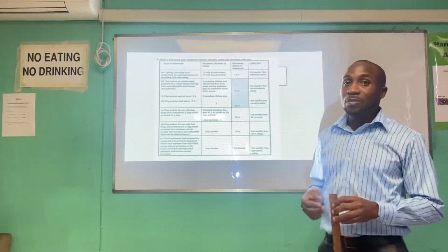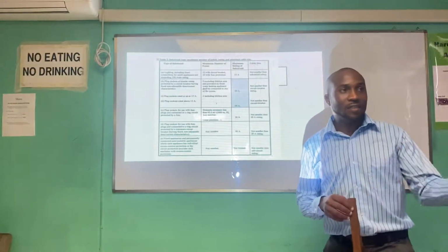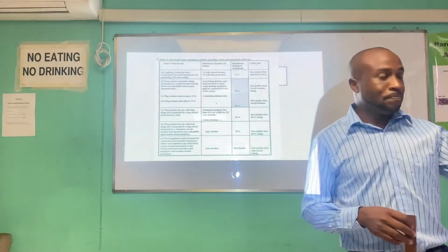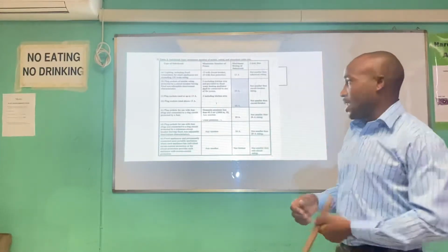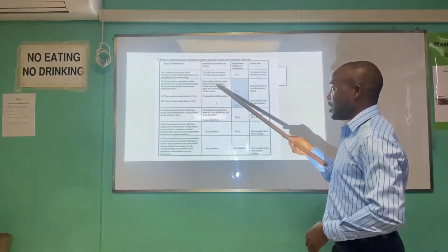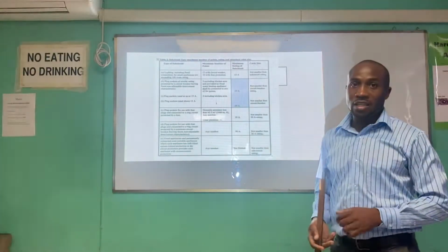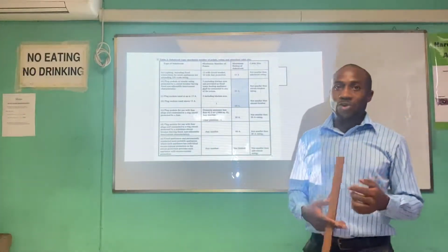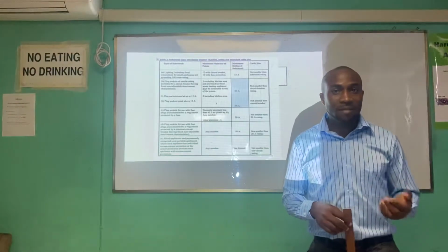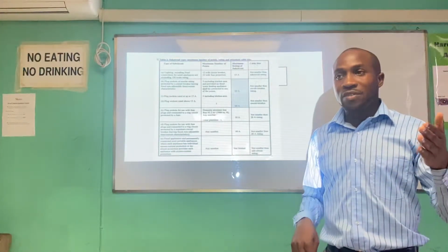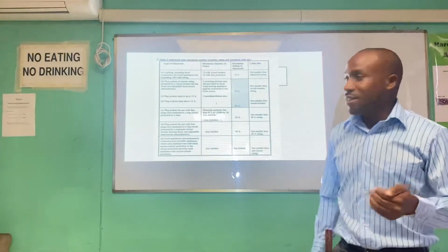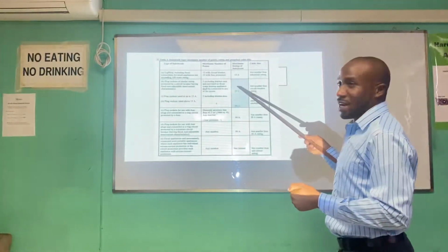But if you are talking about your plug circuits for your living area, your dining area, your passage, and so on, you can easily have up to 5 of these plugs on each 20 amp circuit. If you remember clearly last week when we were discussing the panel and the number of circuits that will go inside the panel, this will play a significant factor.